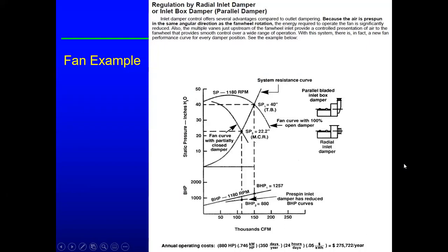And we got a quote from, I'm not sure if it was ABB or Rockwell, one of the big drive suppliers. For all 3 of those, which was a pretty significant purchase, the purchase price on the drives came in at $135 a horsepower, which was pretty darn good. I've seen estimates at 200, 250. So these medium voltage drives are coming down in price.